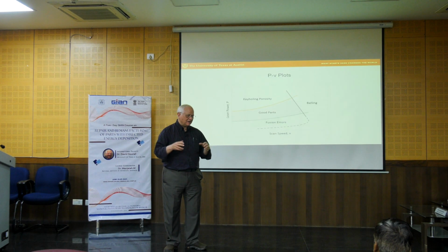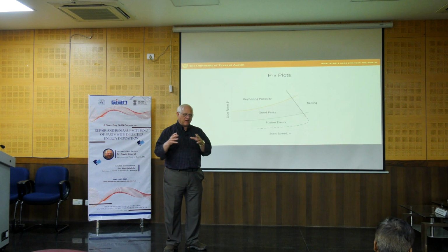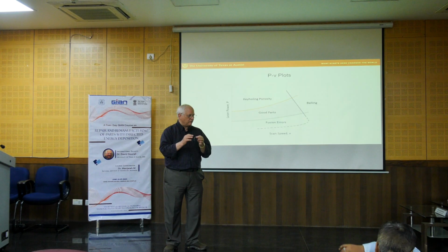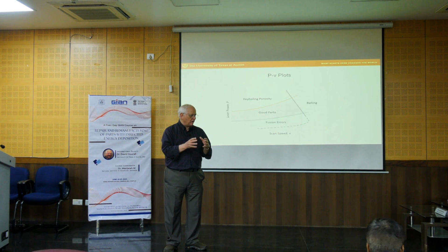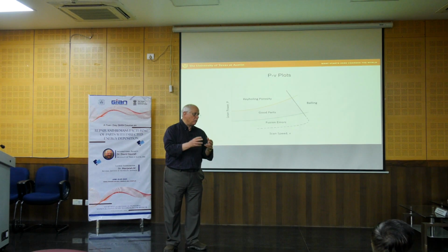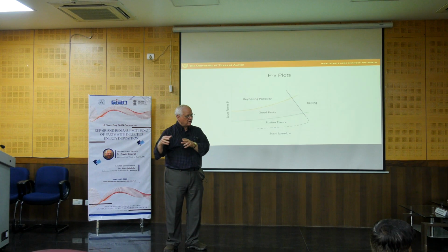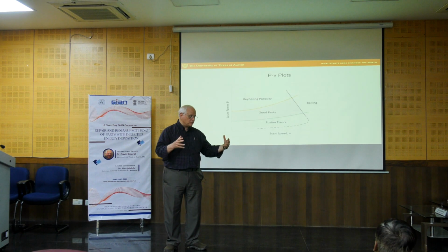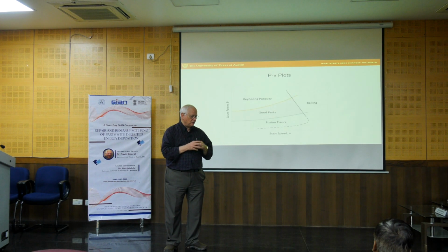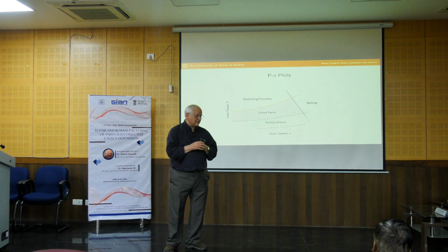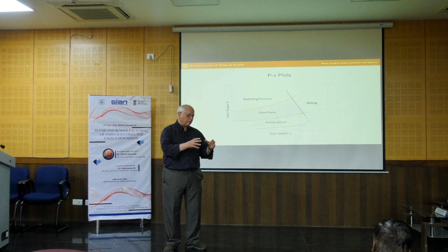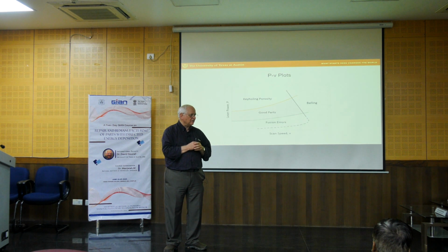But my experience is that powder bed fusion tends to find applications where the parts have fairly complicated geometry, and we don't care that we're building at a low speed. So perhaps small parts with complicated geometries make us lean towards powder bed fusion. Whereas if I have a large part, or I'm not so concerned about the geometry, because you can produce very nice parts in DED in terms of quality, then I lean towards DED personally.